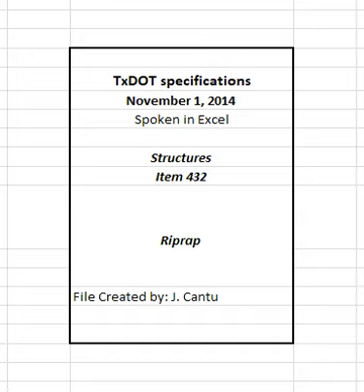Place riprap to its full thickness in a single operation. Avoid displacing the filter fabric. Ensure the entire mass of stones in their final position is free from objectionable pockets of small stones and clusters of larger stones. Do not place riprap in layers, and do not place it by dumping it into chutes, dumping it from the top of the slope, pushing it from the top of the slope, or any method likely to cause segregation of the various sizes.